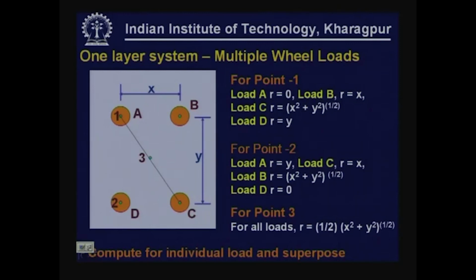For example, if I want to analyze for point 1, what will be the stress and strain and deflection at that point due to all these 4 wheel loads? What has to be done is, we will simply do superposition, and whatever is the stress because of load A, load B, load C and load D at point 1, if you can analyze that, we will algebraically add all of them.